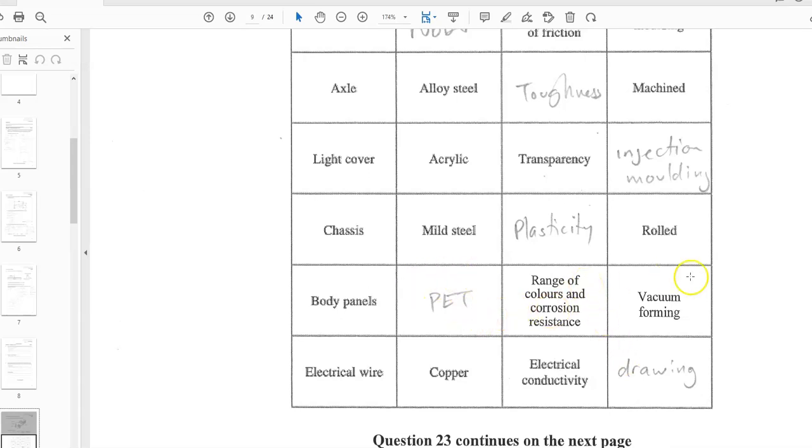Okay, now, plastic. Vacuum forming is a plastic method. What some people may have got that mixed up with is pre-preg applications for CFRP. So if someone wrote carbon fiber or CFRP, I'd pay that as well. But for vacuum forming, we're looking at high density plastic, so HDPE, even PET. I chose PET because that's plastic number 1, and it helped me to remember that. Look, if you went with ABS, I would not allow low density polyethylene (LDPE), but pretty well every other plastic.